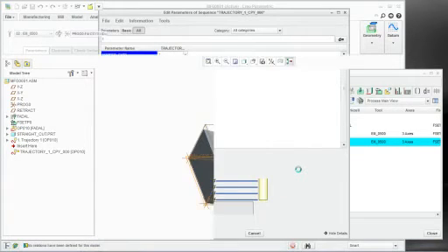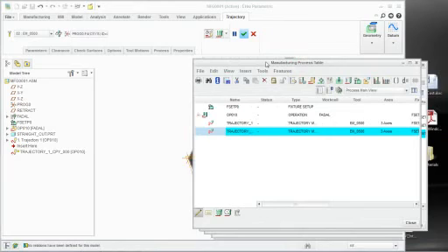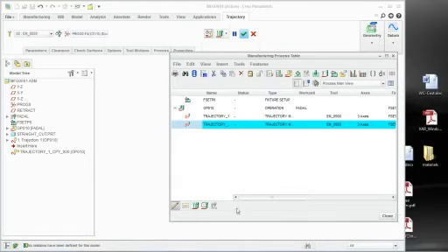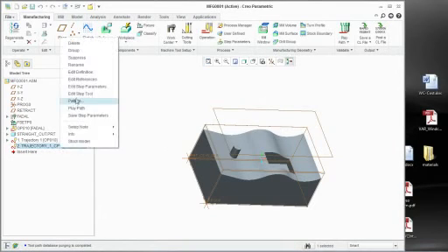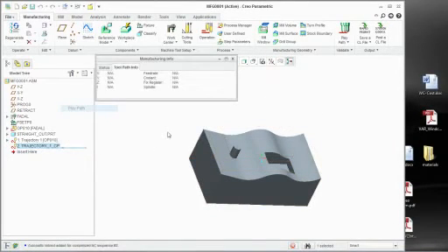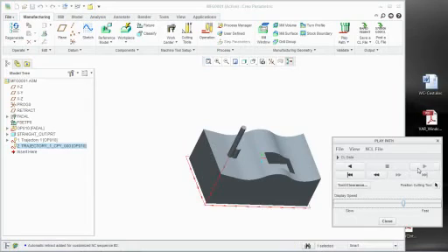And what I've done is copied and pasted that toolpath. There we are. Say OK. And now, when I play this toolpath, all I did was a copy and paste. I didn't have to pick anything. I didn't have to set up my parameters or my tools. I didn't have to repick geometry. I just did a copy and paste, changed the one parameter that I wanted to, and then I was able to create that toolpath. Now, the trajectories actually work well for Control-C and Control-V.